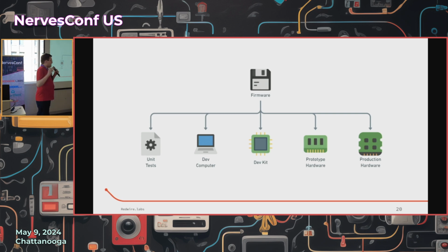And now maybe by that time, you or your company have selected the dev kit that you want to use. That stuff has shipping time on it, so maybe it hasn't come in yet, maybe you gotta wait a little bit for that. You finally get the dev kit, and now you're able to drop your firmware on the dev kit. And then as part of that hardware development process, you typically have a couple iterations of hardware before you actually get to production hardware, right? So you gotta go through a Proto 1, Proto 2, make sure that all that works before you actually ship it out to your customers. That hardware doesn't have the same stuff on it or isn't wired the same way as your dev kit is. So now you need to be able to run the firmware on the prototype hardware, and eventually you get all that ironed out, and now you need to run it on your production hardware. So kind of a whole hardware life cycle here.